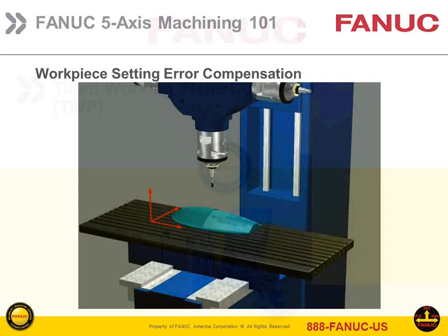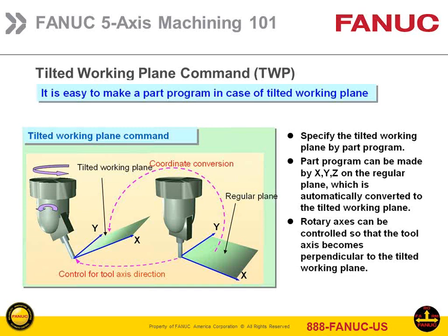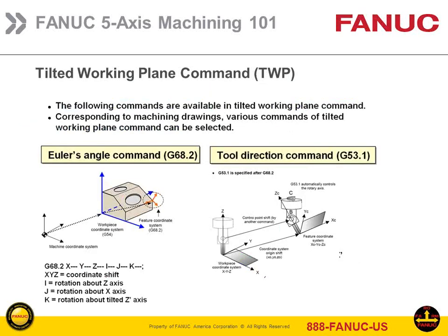And then from there, we're going to get into tilted working plane. And this works in conjunction with our Workpiece Setting Error Compensation. And with this, again, it gives you the capability of where you only have to program based on an XYZ program. You don't have to allow for a plane, because with tilted working plane, with a G68.2 or a G53.1, we can tell it where the part is setting and still use the same program.